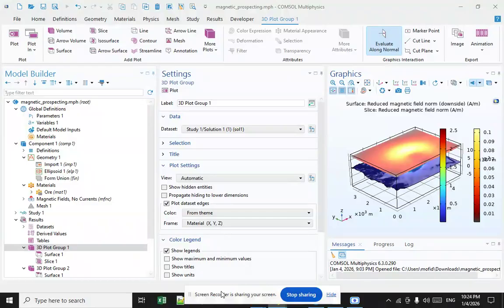And what about the boundary conditions? Along the exterior boundaries of the surrounding box, the perturbation of the magnetic field is assumed to be tangential to the boundaries. The natural boundary condition from the equation is thus that the reduced magnetic field is made tangential to the boundary by the Neumann condition on the reduced potential. Interior boundaries are modeled as continuity boundary conditions.